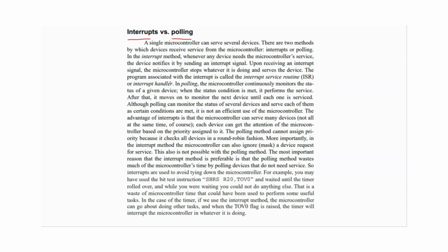But interrupt programming is more efficient in that our device or microcontroller can do one task at a time, and another task or more than one task can be entertained if there is an interrupt from those tasks. So irrespective of the other tasks, it can concentrate on only one or two tasks, and interrupts are efficient while managing more than one task. In this way, we can say that interrupt programming is a better approach than polling in most cases.